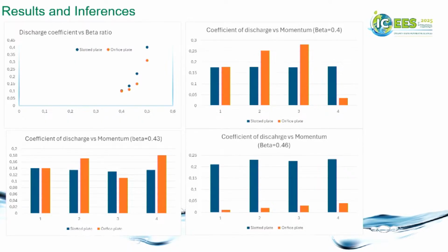The lower the fluctuation percentage, the better the flow accuracy calibration, particularly when you are having different types of flow conditions, vortex shedding, eddy formation, flow separations, cavitations, downstream, and you have other equipment in place that could be impacted when the flow condition becomes adversarial for the equipment on stream.